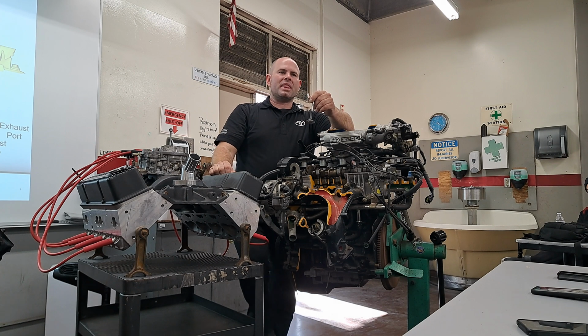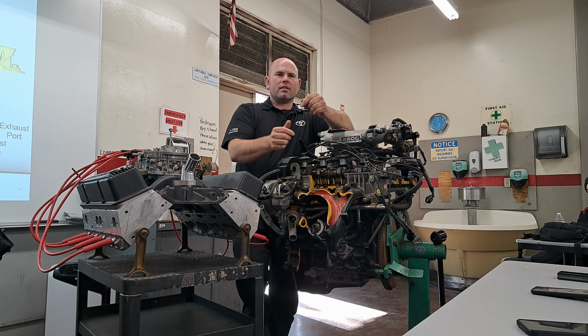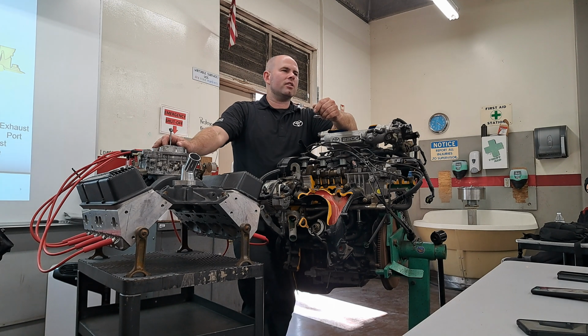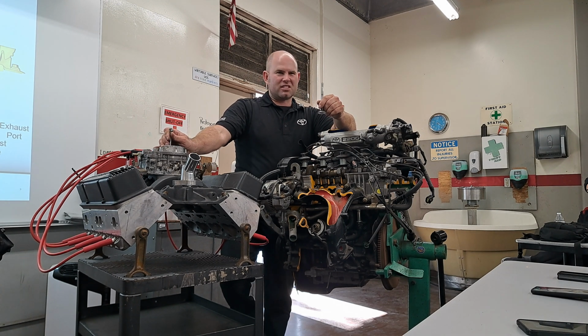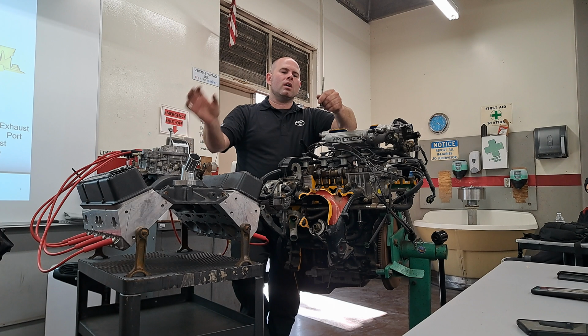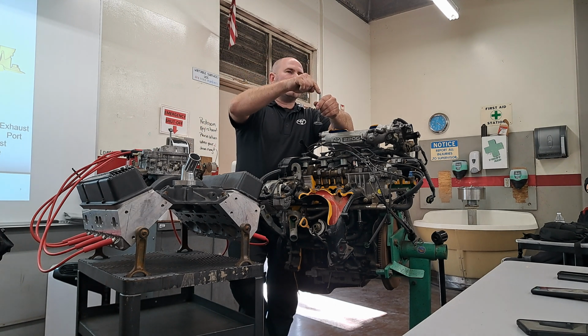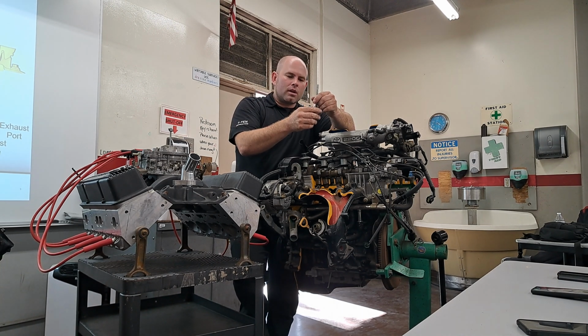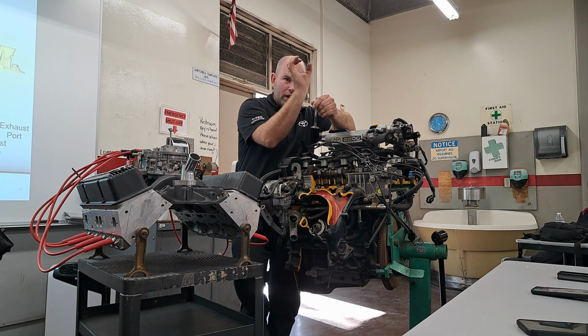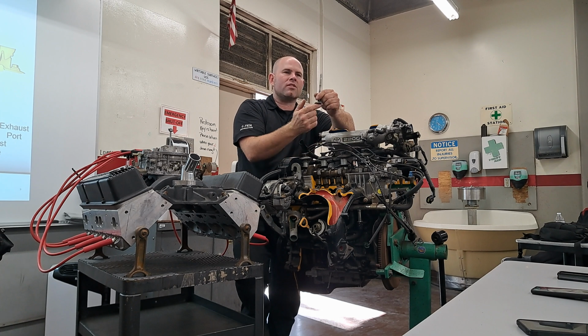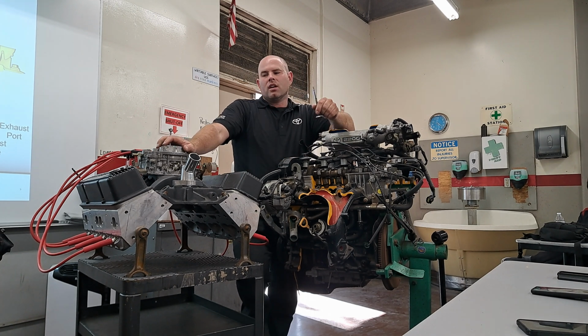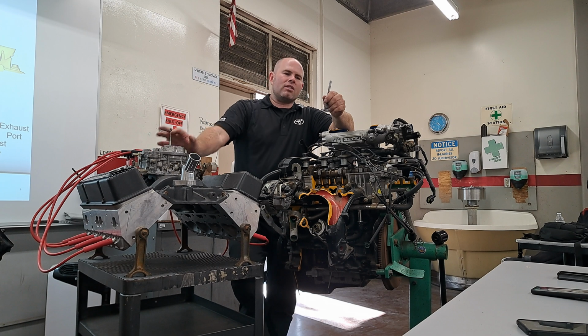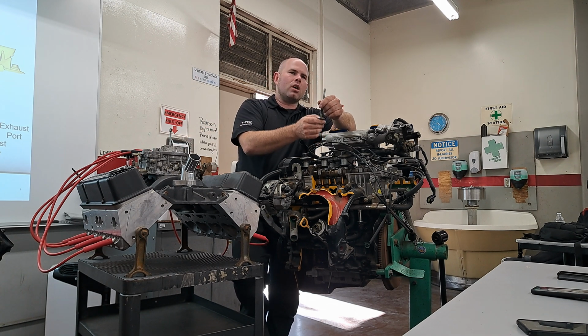But then the valve needs to close, right? Think about this. What makes the valve close? Oh, you guys know a little something already. So the cam pushes down, but then that's a crank. Cam's a little smaller, got a lot of bumps on it. So it pushes down, cool. But then the cam has the ramp ends, and then the valve spring pulls the valve back up. That's the whole action. So kind of the difference is the cam opens it and the valve spring closes it.